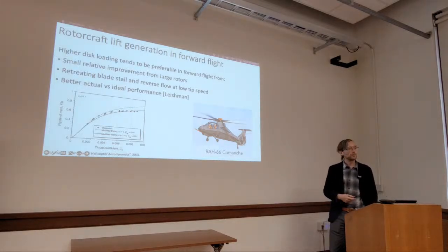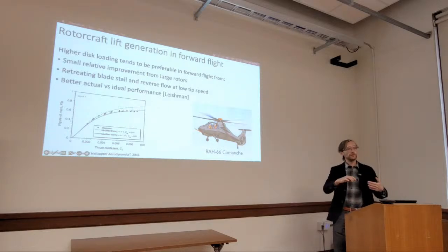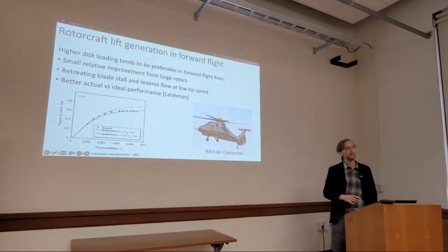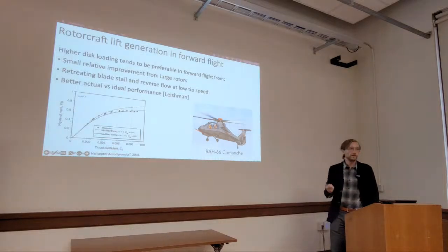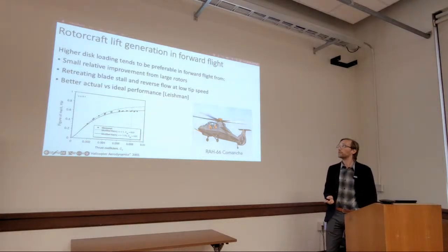There are other aspects of forward flight that favor a higher disk loading. Mostly issues related with retreating blade stall and reverse flow, which happens when the velocity of the air relative to the retreating blade becomes so small that it can incur blade stall, or even negative velocity, incurring negative lift. So that's something that's absolutely undesirable, and having a higher rotor velocity, which correlates with higher disk loading, is preferable.